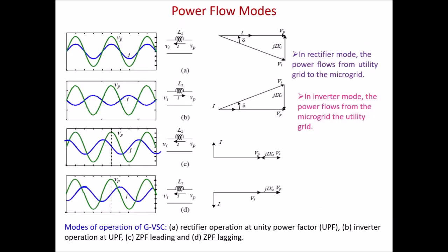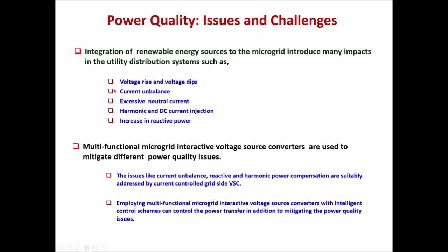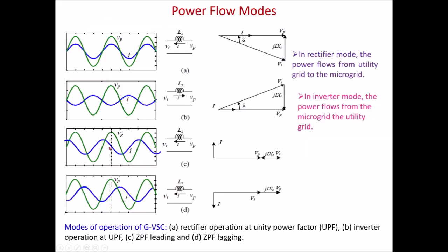Apart from that, if you come to the grid interactive mode, the most important power flow modes are basically rectifier mode, inverter mode, and the zero power factor mode. So what are these modes about? It is about power flow into the grid, power flow out of the grid, or no power flow but reactive power support. So these two points correspond to the reactive power support.